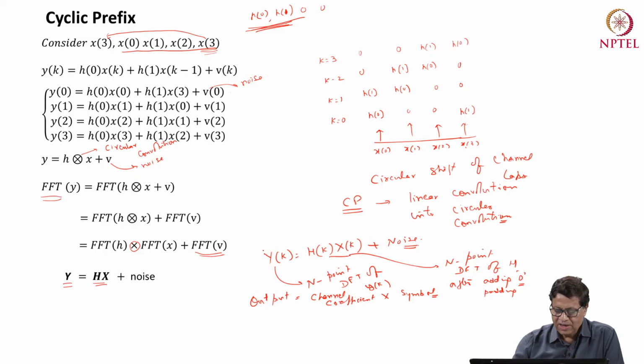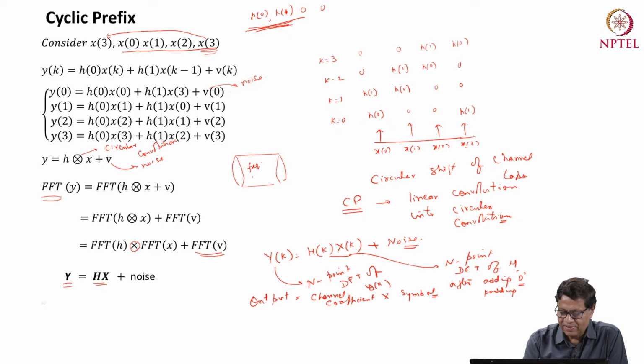So what actually has happened here: earlier we started with a frequency selective single carrier. Now we have broken this into N parts, each modulated by a subcarrier. So we have made N parallel streams, and all those parallel streams were combined and transmitted.